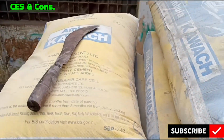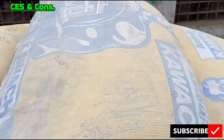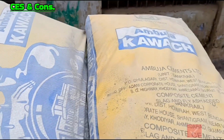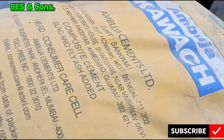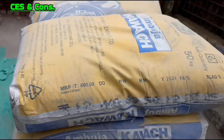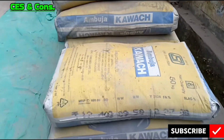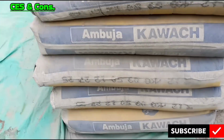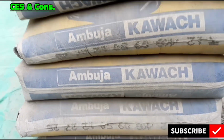Number 6. Storage of cement. This is most vital and as guided in IS 4082/1996. This must be stored in dry, leak-proof godown. Stack not higher than 15 bags. Used within 3 months of manufacture for best result.